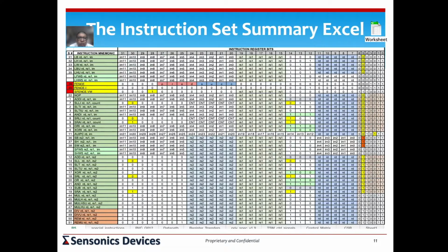This is a very low cost and easy method of doing something that would later require very expensive cycles while verifying the detailed logic. Plus, there's also another advantage of using this Excel, is that the various bit patterns that you get out of here can be directly read out from a Python program, for example, that you could write, which we will talk about briefly, while you're generating control for your final data path. And those will pick directly from here. So you don't have to enter this data multiple places or multiple times.